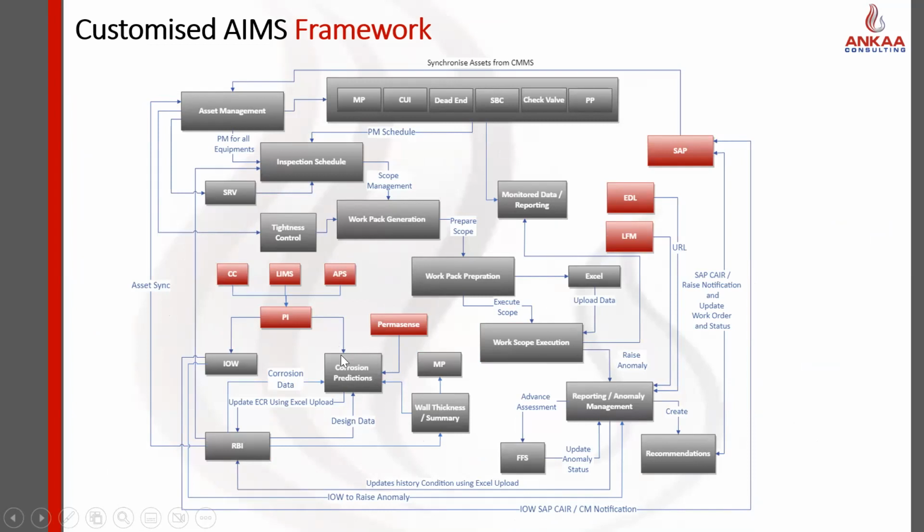They wanted to build the corrosion prediction algorithms to optimize their corrosion prediction between correlations and the actual data. So they've built that, and they've also built integrity assessment with a particular focus on specialist components like mixing points, corrosion under insulation, dead legs. This is where you're most likely to get corrosion and damage mechanisms.